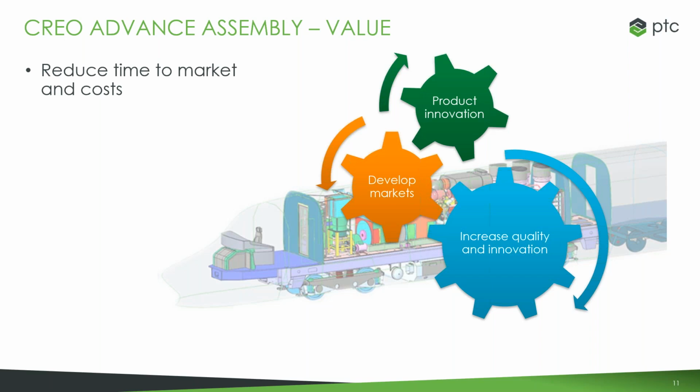So you can also drive predictable changes from the skeleton model. You're able to control your references to keep them minimal and to those key pieces of geometry. You're able to see your references with the reference viewer. So you're able to predict what's going to happen to your model, so you can make these large scale changes even at the end of your design.